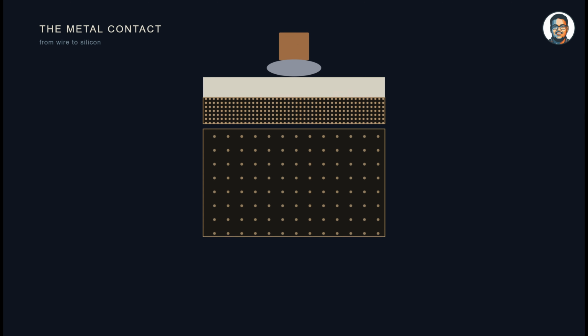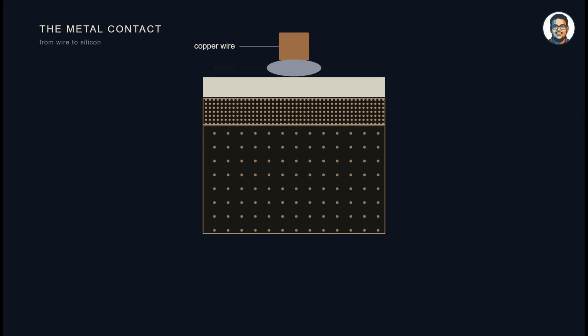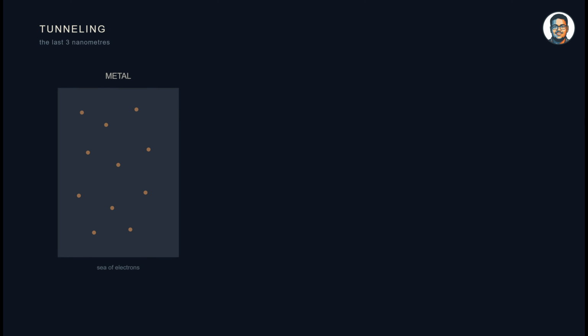The copper wires forming the circuit are not directly soldered to the silicon, but there is a metal plate which too is not in direct contact with the core body of the silicon. Between them sits an extra heavily doped patch of silicon itself with the same dopants as the core body, but 100 times more concentrated, to make the Schottky barrier ultra thin for quantum tunneling to be possible in the direction of the external voltage. Look closely.